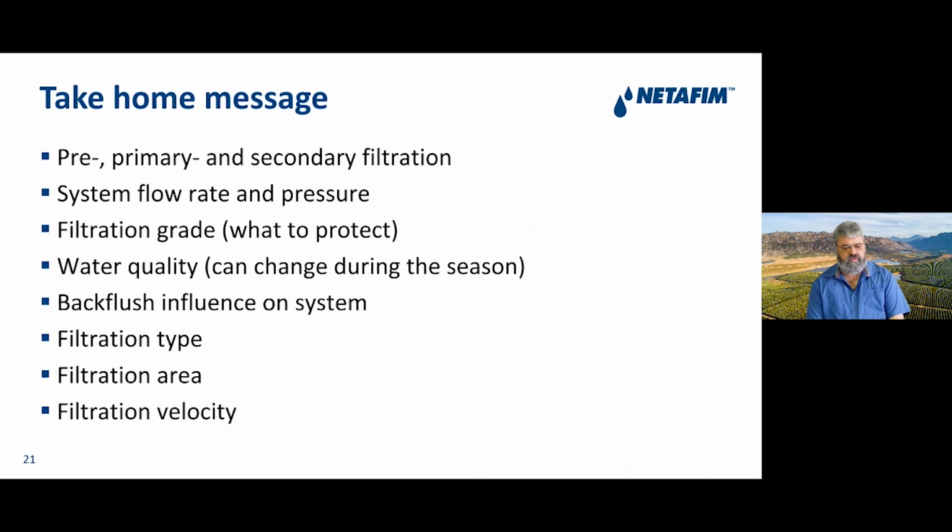Then the last 3 things, the filtration type, area, and velocity. They're all interconnected. At Netafim, we set norms for all three different types of filtration, and we follow those norms. And these norms are generated over years of experience, and they may seem sometimes conservative, but it really works.